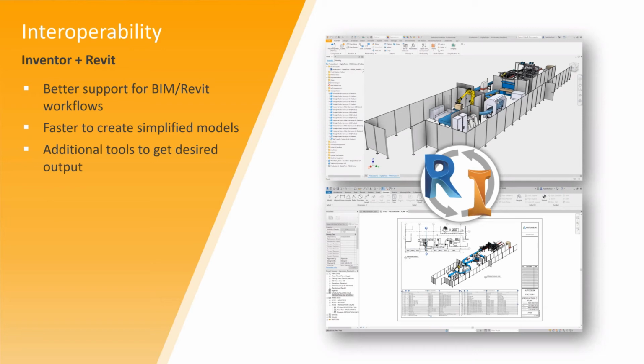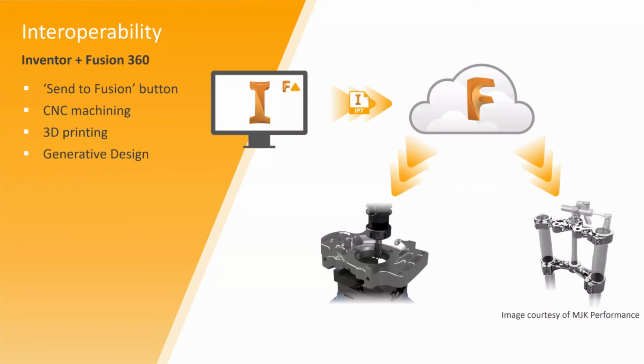When we create this, we can simplify the model coming from Inventor and going into Revit, and then use that as a connected item. A link to the original model is retained, and the associativity functions correctly within those items. Very handy functionality again.